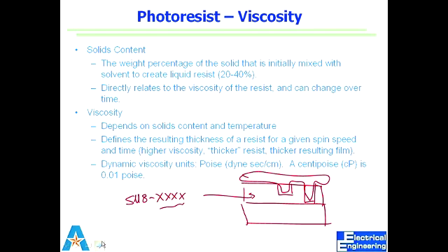Many resists are just not meant for the process you're doing sometimes, because you might have high aspect ratio features and your resist will just fly off and would never go inside to cover those trenches, right? So it would be too less viscous for you, right? So we have to see our application and have to know what resist will work for that specific application.